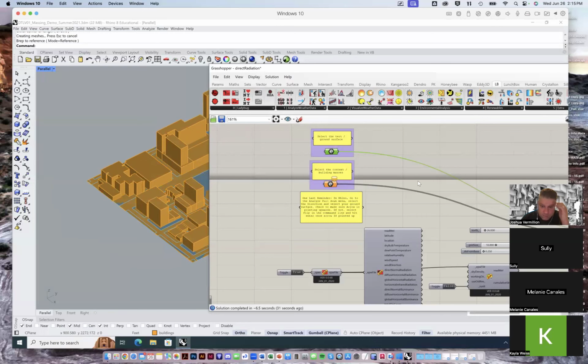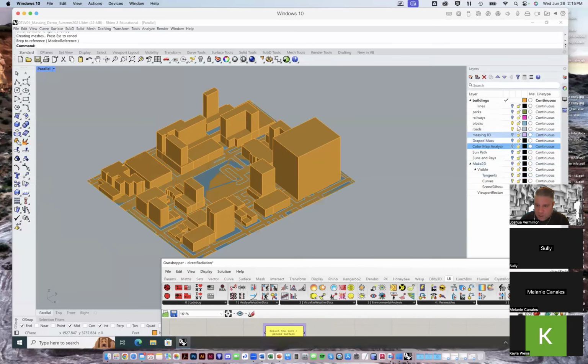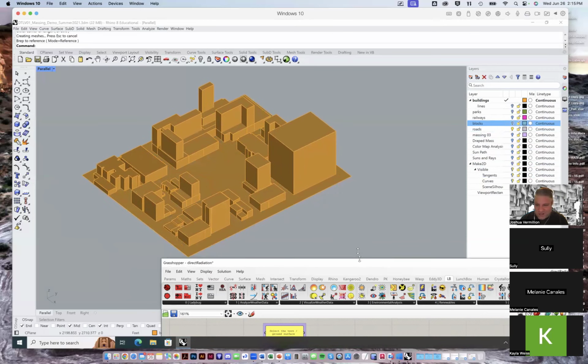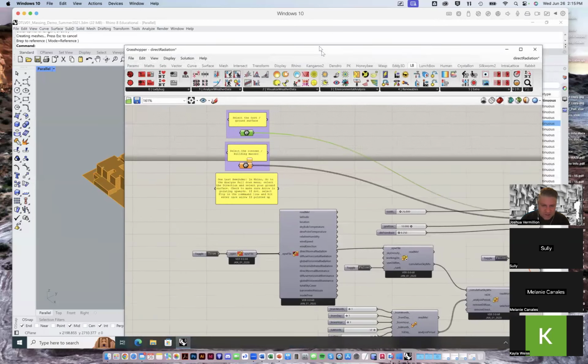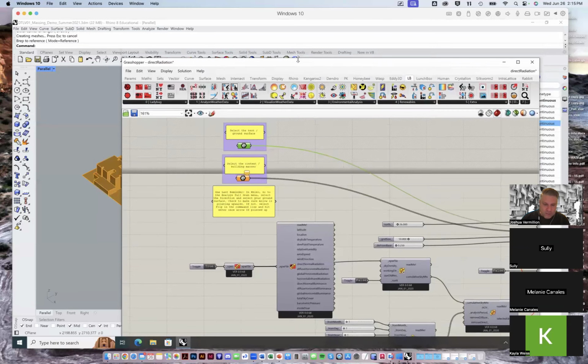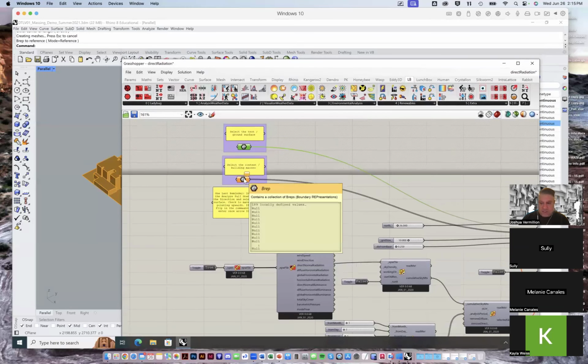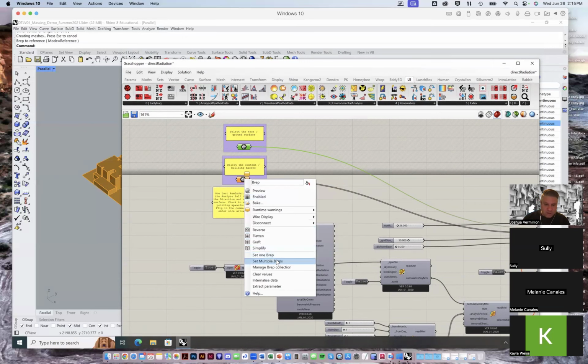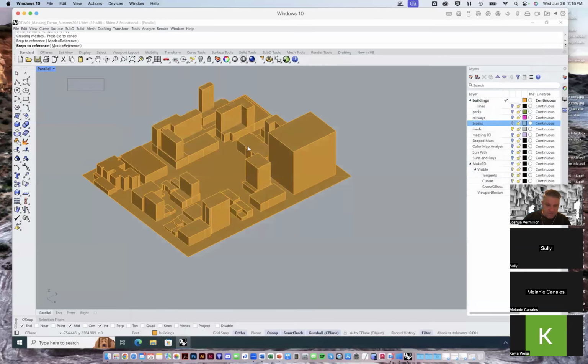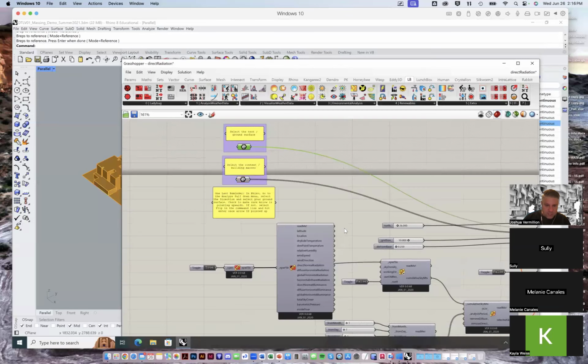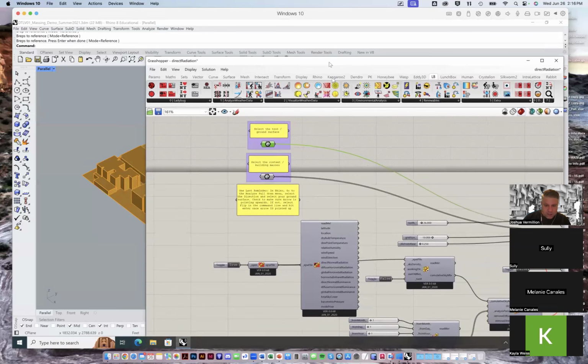All right. For our purposes, I'm just going to turn off these blocks. They're not really casting too many dramatic shadows anywhere. Then I'll select the context and building masses. That's important because those cast shadows. You can select which of these, or all of these, that you want to actually have an effect on the solar geometry.